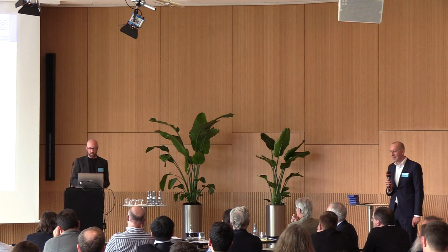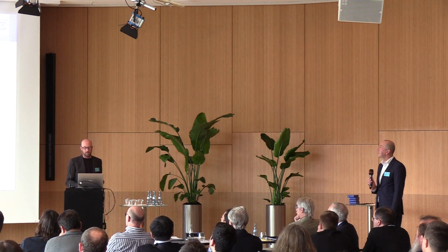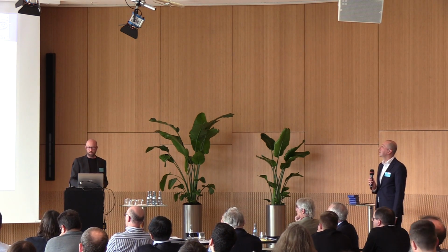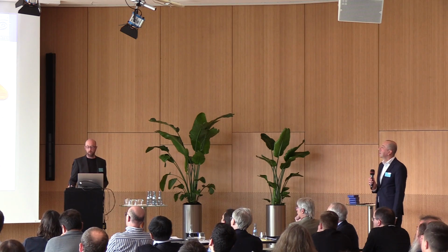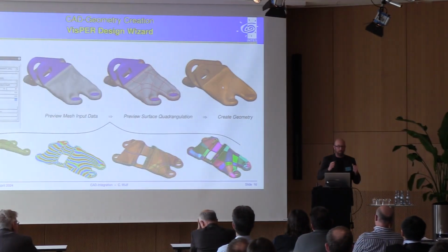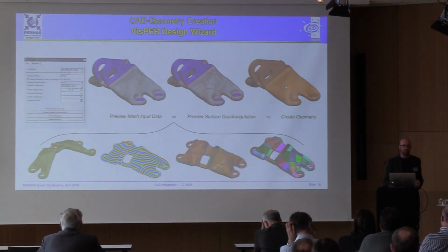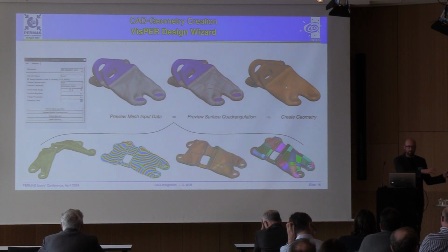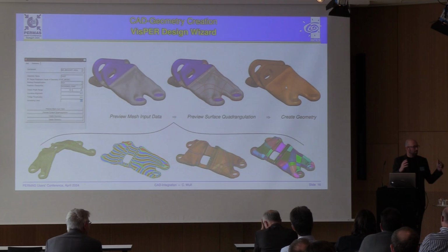This depends. You know, this is what I told you. During this last step, we have some opportunity for smoothing. So this depends on the smoothing tolerances you choose. You can stay very close to the triangle mesh, but then with less smooth results. Of course, a reanalysis of the result generated automatically by this process is necessary.